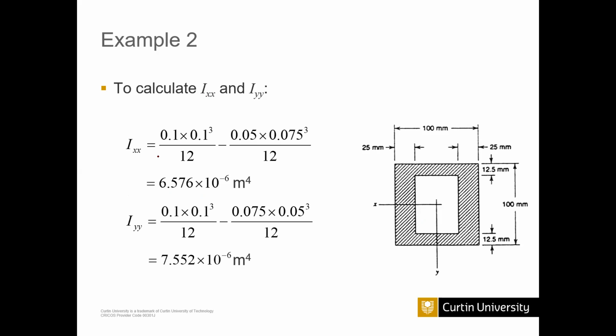I think you know how to find the second moment of inertia. This is a square shape, so you know the equation, BD cubed. If we have a cross section like this, it is BD. What you need to do is find the second moment of inertia in the x and y directions. If it is Ixx, they consider this the x direction.